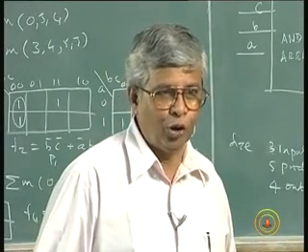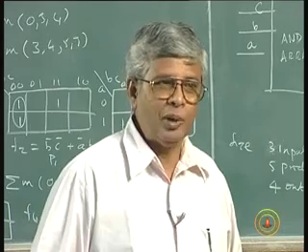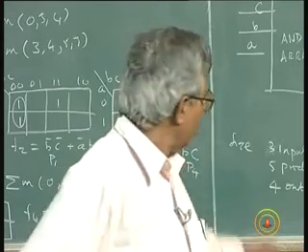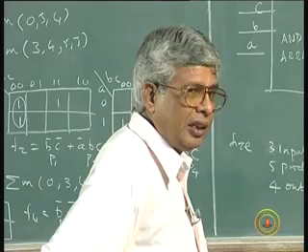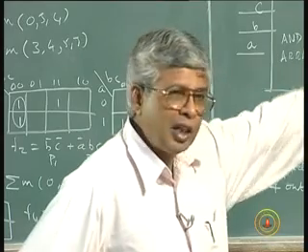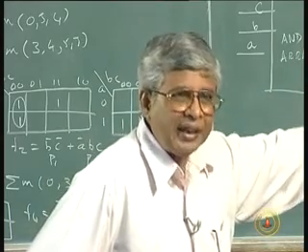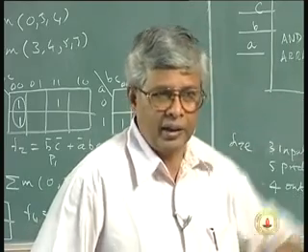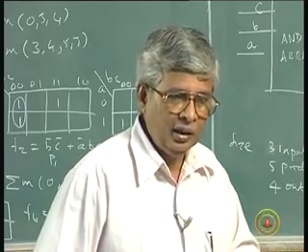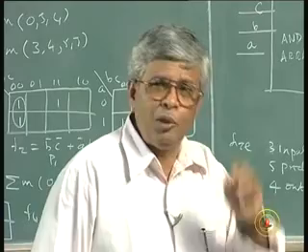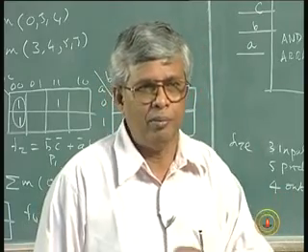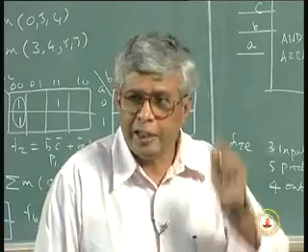Of course you won't do it; you don't want all the 4 outputs to be the same. In principle I can have each of those outputs have 5 product terms, but my specification requires only this type of thing. Up to 5 inputs I can connect. Each of the product terms can go as an input to the OR gate for each of the functions. There is a programmability similar to the ROM programmability, which you understood in the last lecture. Same, there is no change. There is an additional programmability here.